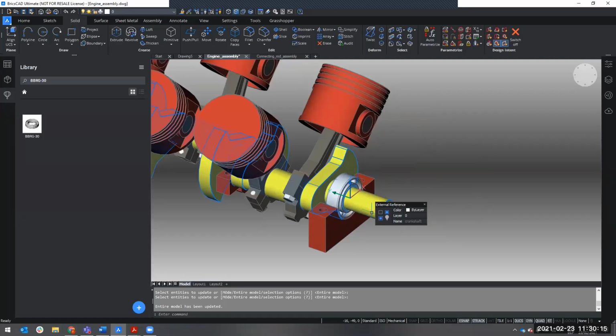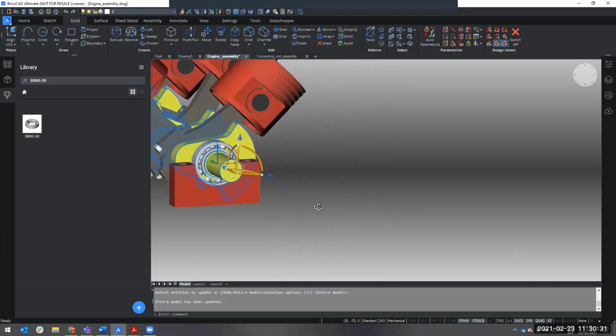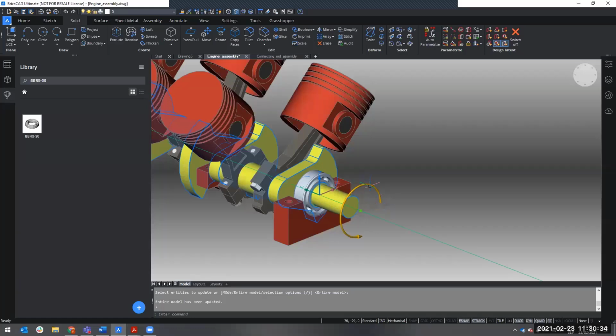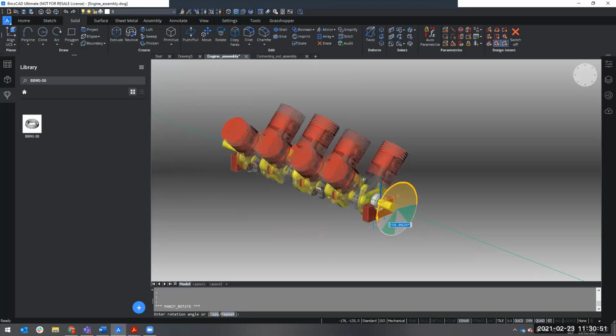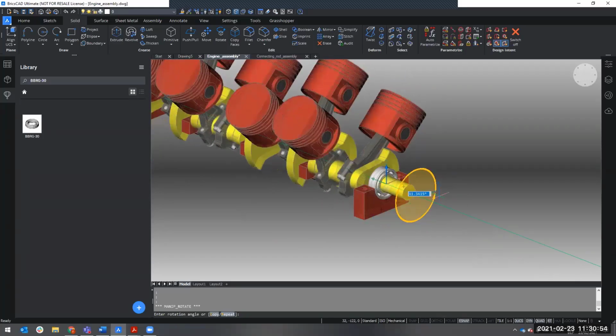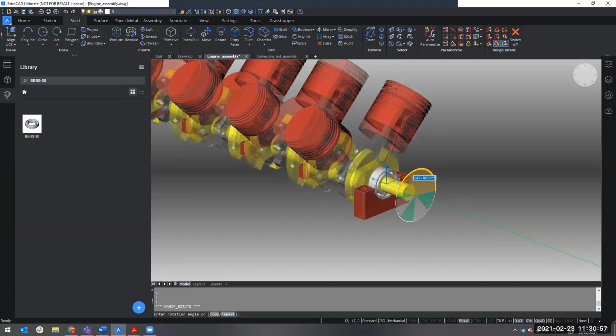And we can do that by rotating the shaft. So you can do that by clicking on it, like a little longer click than usual, just a normal left click. And then you can choose the rotation direction according to the axis, or you could straight away use DM rotate, but I will show that in a minute. So I will first do it with this. And if you now see, this is actually giving you, now it's going in increments, but it's giving you a preview of how this assembly works together in a kinematic way, kind of.